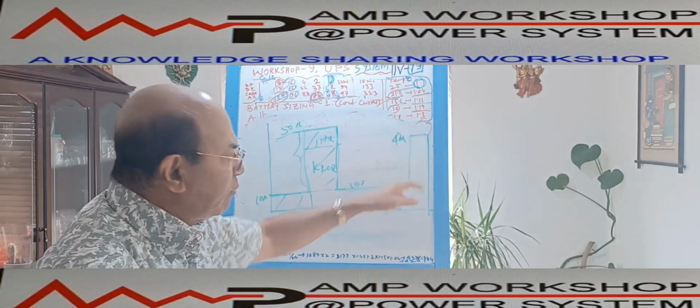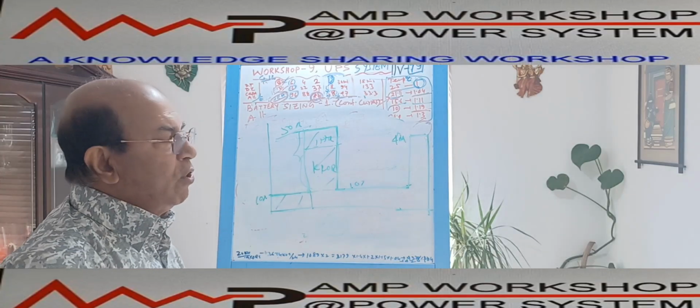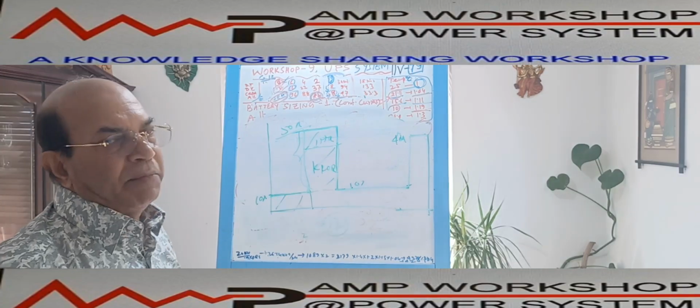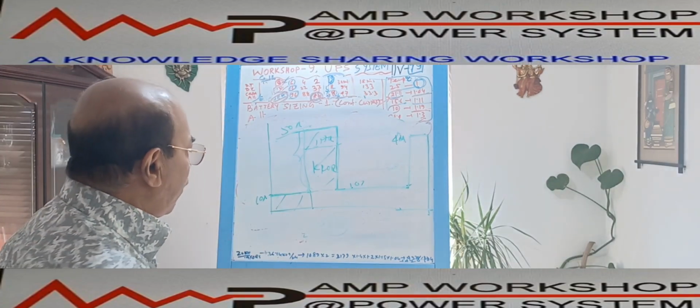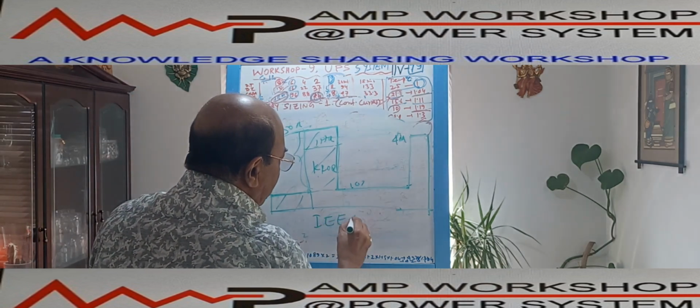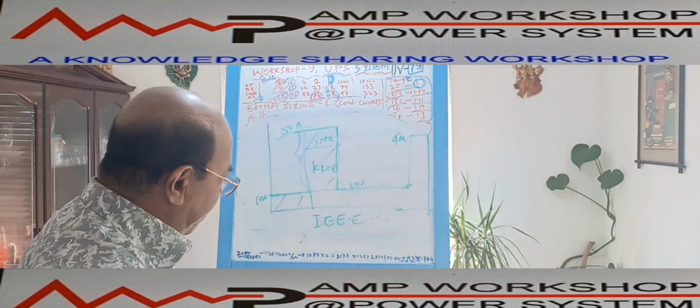So for each part, the rate of discharge factor will be different. We have to calculate this rate of discharge factor, and from it calculate the individual part ampere hour, and then sum it up. That also will follow IEEE 485. We can do this calculation for the variable load in the next video, video number 80. This is one of the things.